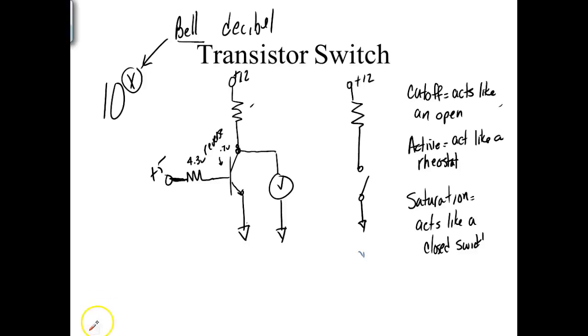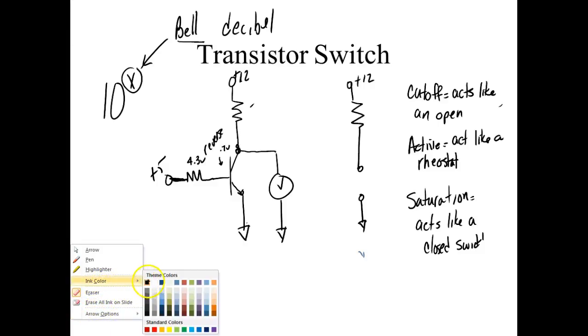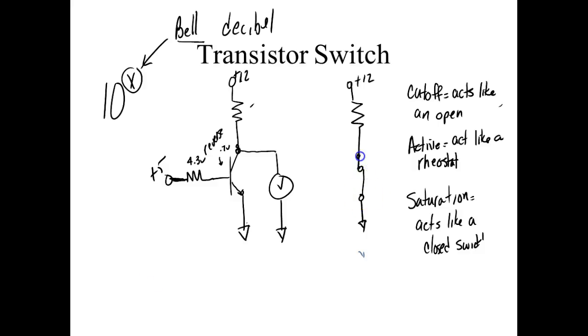Okay. So what I just did with that 5 volts is I came in here and I closed this switch. And I'm taking my voltage measurement right here. So what I've done is I've connected the top of the light and the bottom of the light at exactly the same potential. Now that could be 5 volts and 5 volts. Here we're using common. So if I have 5 volts on one side of a resistor and 5 volts on the other side of the resistor, how many volts is it dropping? It's dropping 0 volts, right? You understand?